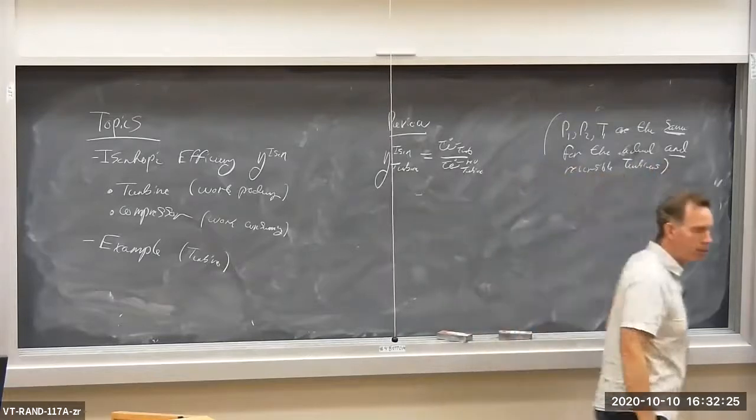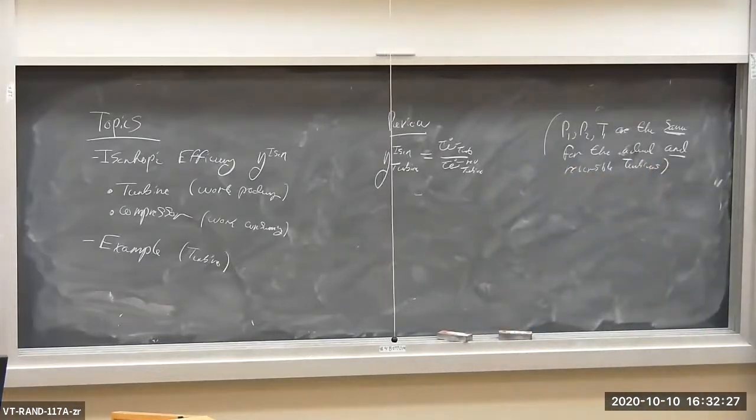We have to start off with the same temperature and have the same pressure drop, else it's not fair comparing the two turbines. We're comparing a real-world turbine that operates between two pressure limits with the same inlet pressure with the maximum possible work produced by a reversible turbine.